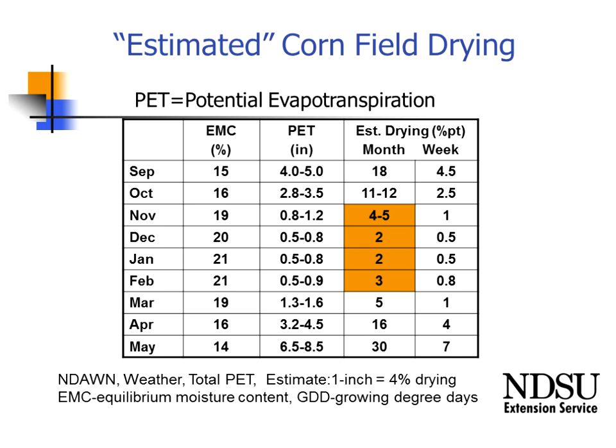And so what I did was to look at the potential evapotranspiration calculation, and this is again, like I said, for North Dakota. We looked at what was the PET, or potential evapotranspiration, based on our North Dakota Ag Weather Network. And what I found was that there was a pretty good correlation between this potential evapotranspiration and the kind of drying that we might expect.